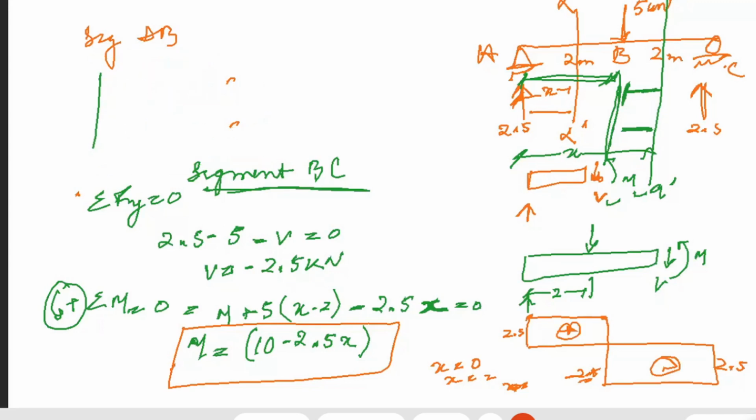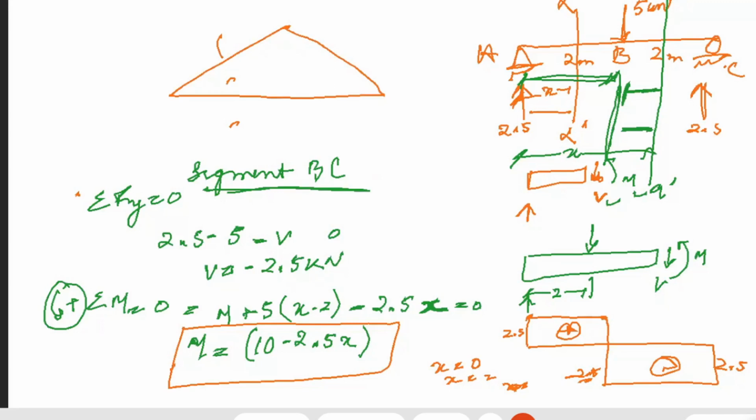And similarly you can draw its bending moment diagram also, and you already know for this point value your bending moment diagram will be, it's a sagging moment, a straight line, it will be linear. But your moment will vary for this very portion as M is equal to 2.5x, and here your moment equation will be M is equal to 10 minus 2.5x for this very portion.